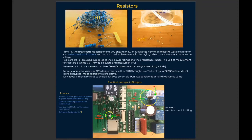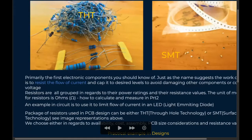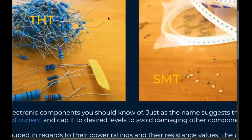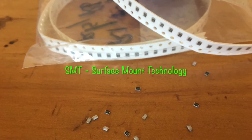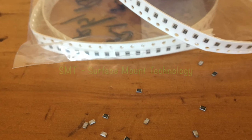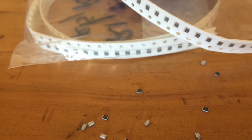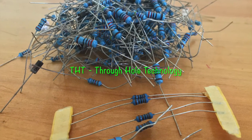Resistors do come in two types of packages. We have THT, that is through-hole technology, and SMT, that is surface mount technology. As you can see on the images above, if I zoom in, these are smaller packages. These are used when you care so much about the size of your design, and you don't want your design to be so big. THT, you use them everywhere, you can just use them on the go.